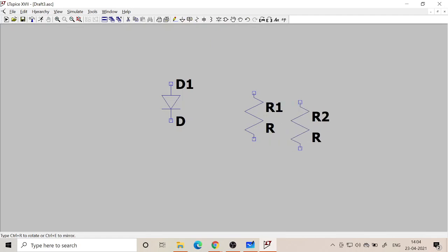So what are the components that we require for it? We obviously require a diode. You click here, bring the diode, and then right click. You can choose the next component. We require a load resistor, so I am choosing a resistor. If you again click left, then repetition of the same component will happen. So in order to avoid it, you click right, that will disappear.